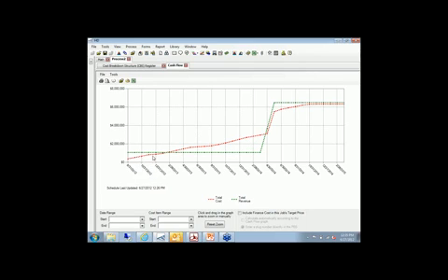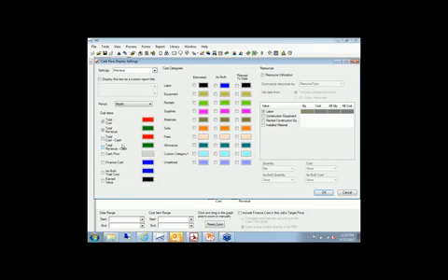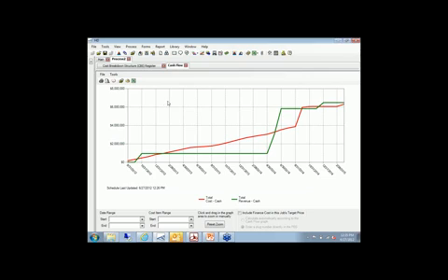Right now, we're looking at this based on, let's say, earned values. In other words, when does the work occur? If we graph it, we could also graph it based on what we call cash values. Okay, so if we look at it based on cash, that is going to reflect delays in terms of, if we're the contractor, how long does it take us to submit our bills? How long does it take to get paid? Okay, so you can see in this case, even though we end up where we want to be, the green line's above the red line, there's a pretty significant period of time in here where the costs we're expending are actually exceeding the revenue we have, the income we have on this project.